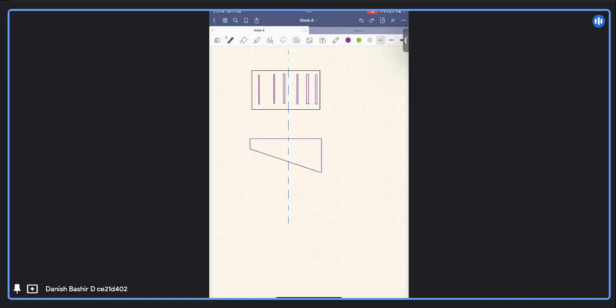Look at this strain profile here. You can see that the whole column section is in compression. So if I extend this profile like this, with another color, I will have a point where this compression strain becomes 0. So there will be the point where I will have my neutral axis. If I draw a line along this point, you can clearly see this is the neutral axis.